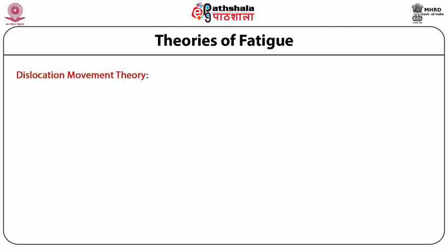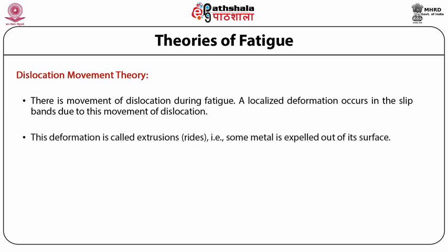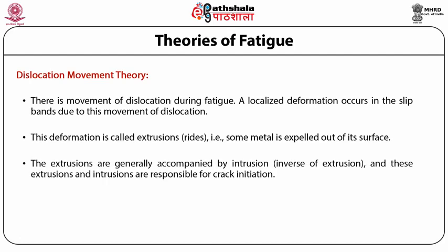The next topic is dislocation movement theory. There is a movement of dislocation during fatigue. A localized deformation occurs in the slip bands due to this movement of dislocation. This deformation is called extrusions or ridges, that is, some metal is expelled out of its surface. The extrusions are generally accompanied by intrusions, that is the inverse of extrusion, and these extrusions and intrusions are responsible for crack initiation.